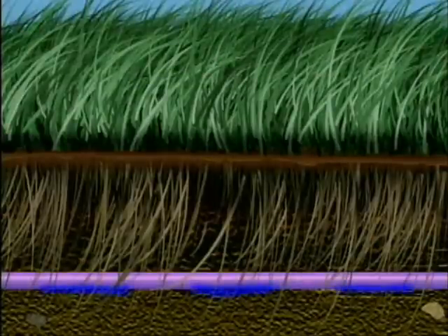Drip laterals are installed at depths ranging from 6 to 24 inches, with the most common depths in the range of 8 to 12 inches. The real benefit of a drip dispersal system is to place the water into the active growing zone in the soil. This allows plants to use the water and nutrients.